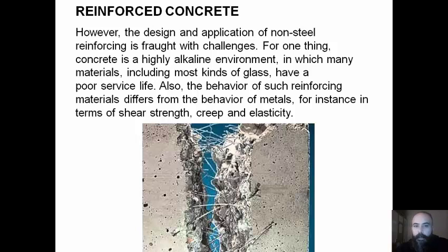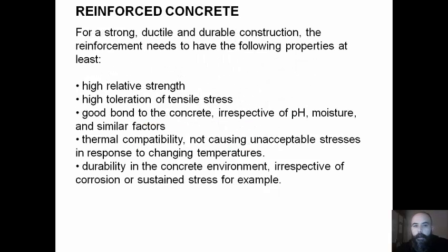For one thing, concrete is a highly alkaline environment, in which many materials, including most kinds of glass, have a poor surface life. Also, the behavior of such reinforcing materials differs from the behavior of metals, for instance in terms of shear strength and creep and elasticity. For a strong, ductile and durable construction, the reinforcement needs to have the following properties at